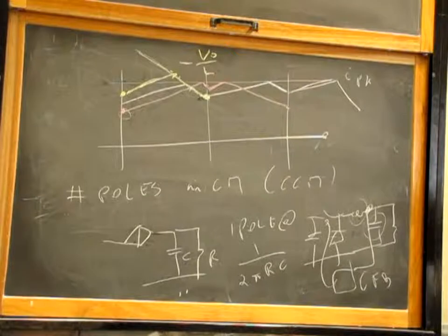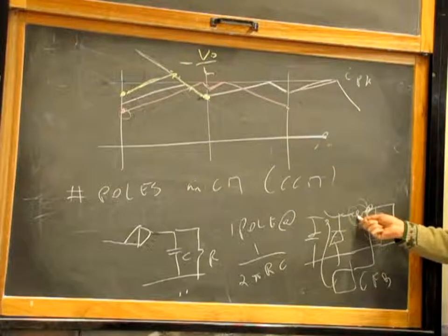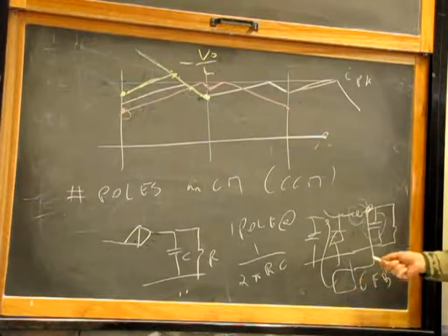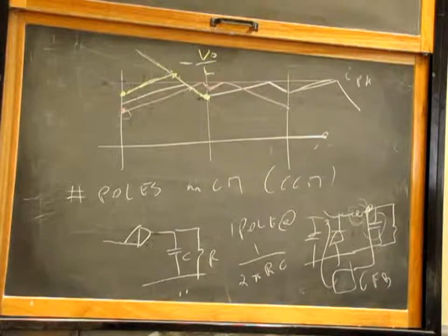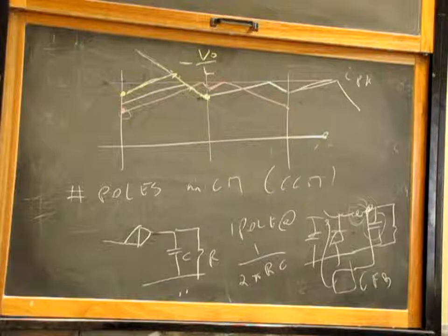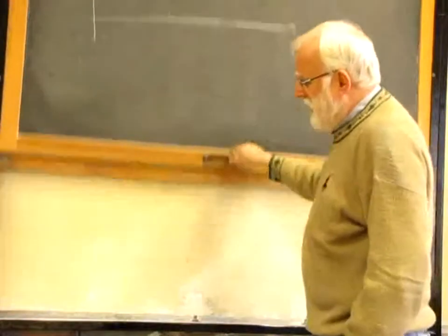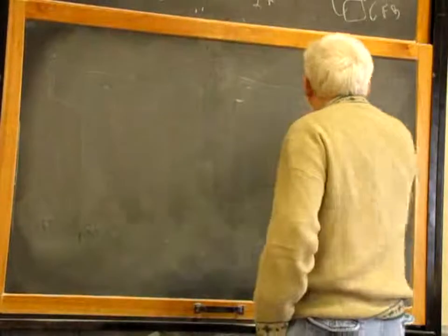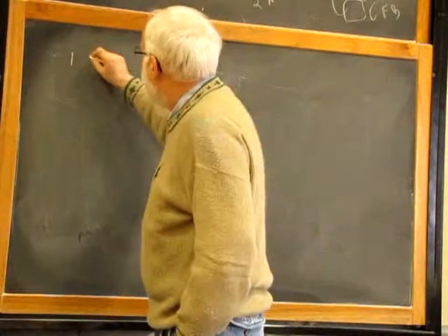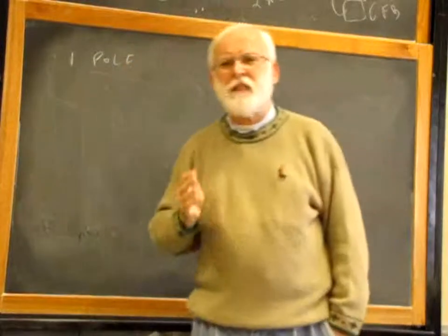So, somebody started to look for the pole associated to the inductance in this feedback loop, and he discovered that this pole is moved to high frequency, above 1/2 of switching frequency or somewhere like that. And so, if we have to discuss the number of poles, we can say, technically speaking, we have one pole. This is what you do when you make a design, most of the time.